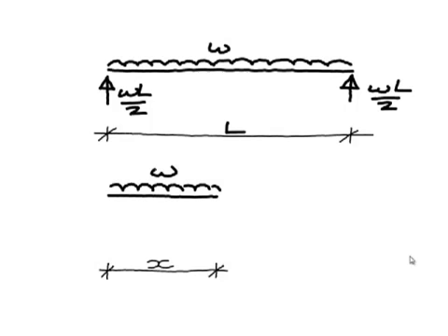So let's look first at the equilibrium. The shear force at the cut, if we assume that it acts downwards, must equal everything acting up the page. And everything acting up the page will be WL upon 2 minus W times x.